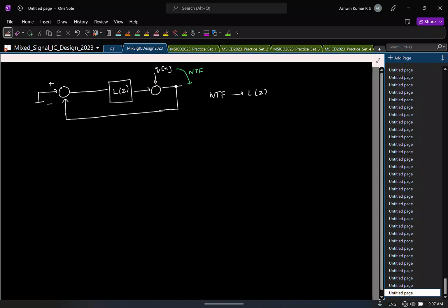Cool. And you know that this is realized using switch capacitor circuits. So explicitly I will show that the signal is sampled prior and then we are filtering. Any switch capacitor circuit, the input stage looks like this: you have something that samples the input, and then you have the rest of this.